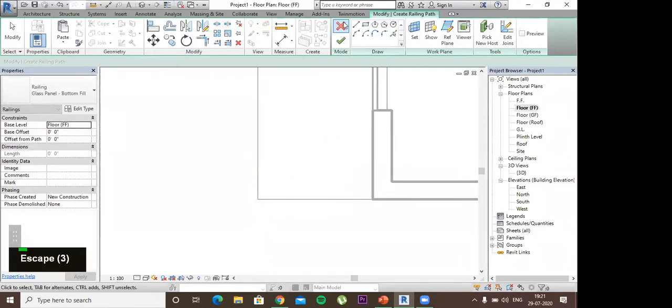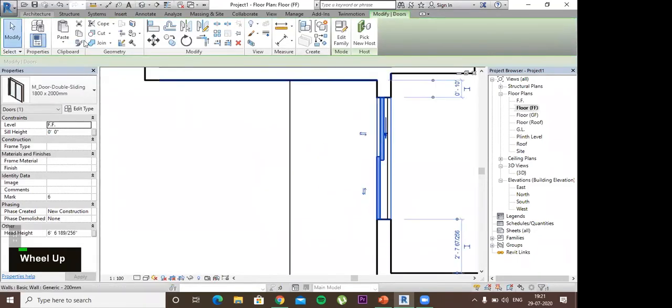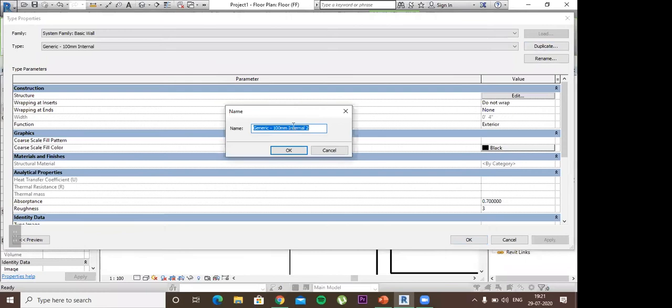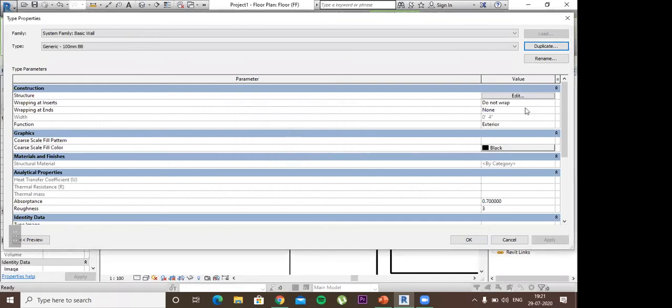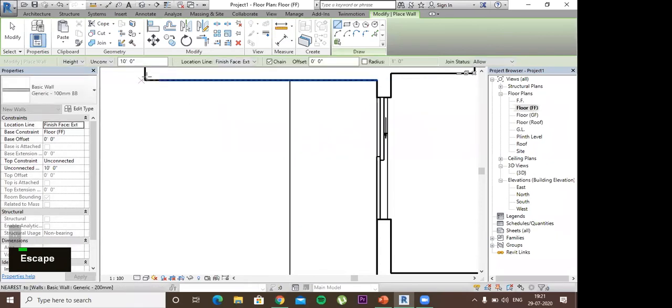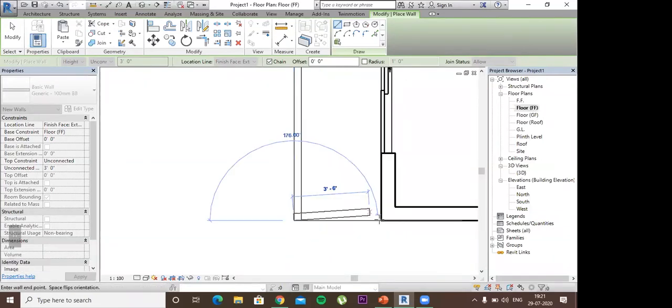But before creating a railing, I'd like to create a boundary on which we will be creating a railing. So we'll make another wall, create a duplicate, balcony boundary, BB stands for that. Okay, and that's pretty much it. We'll keep its height to 3 feet, then inside.